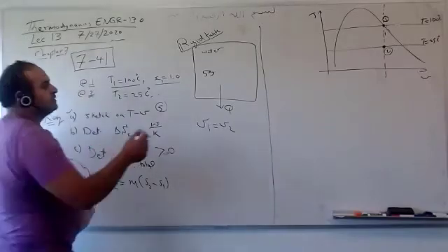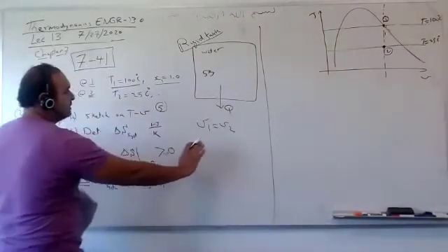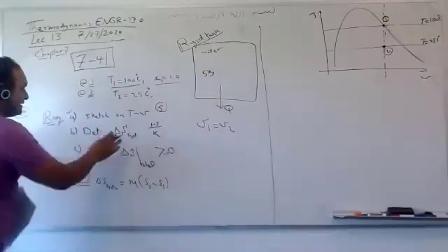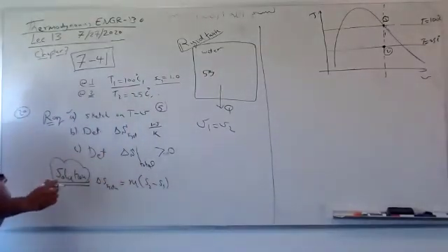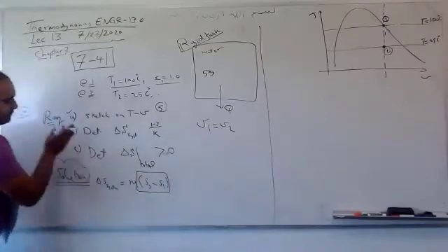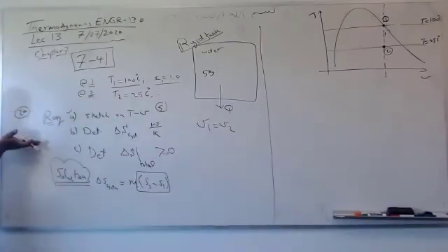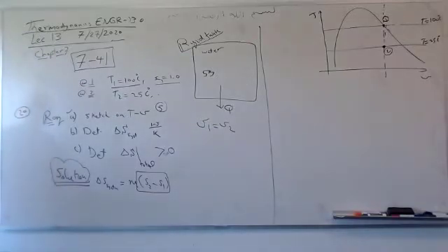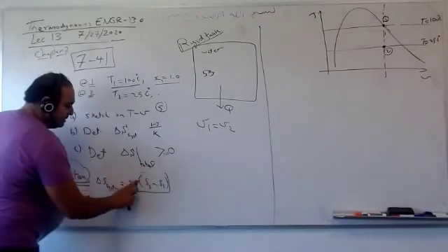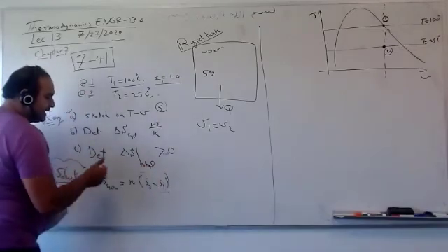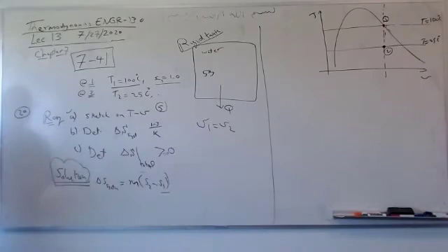This system does not have constant temperature, for example. The surrounding, yes, but this system, no. So for the system, this one was number 2. We have number 1, constant temperature, steam table, solid and liquid, ideal gas. You remember these 4 cases, guys? This is number 2. And of course, you remember the definition always, Q over T. If I have Q function of temperature, I can integrate to obtain S function of T. So always remember the basic definition and the special cases. This is the second case, which is steam table. So I wish to have S2 and S1.